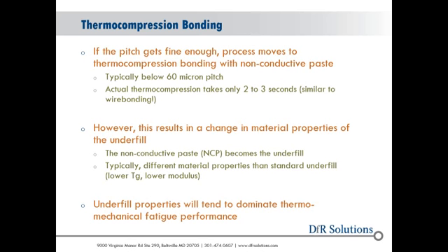Now, of course, I can't put it all in a single reflow oven, so there are, again, some trade-offs there. One of the difficulties is that this non-conductive paste now becomes my underfill, right? I'm no longer having the classic underfill process, which is post-assembly of the die to the substrate. My NCP is my underfill. So it helps me with my process, and it becomes my default underfill. So now I've changed the material, and there are other material requirements for NCP beyond the standard underfill because it becomes part of the assembly process.